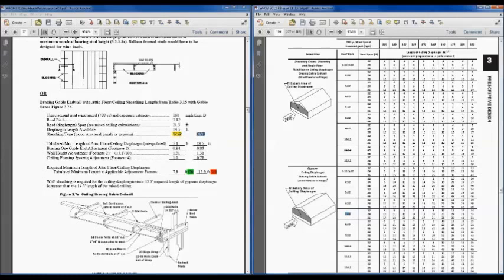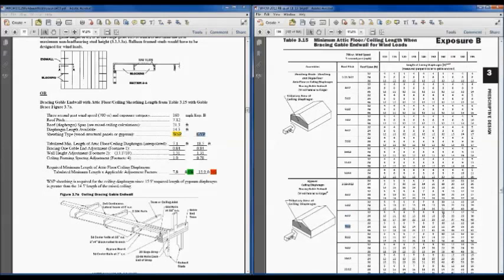Something doesn't seem right here for that interpolation. Give me just a second to get my bearings. Sorry about that. I may have misread that table at some point, or maybe I'll figure it out here in a second, but I'm thinking it's supposed to interpolate between 21 and 35 feet. We, for some reason, have 18 feet here, and with the adjustment factors, it ends up showing 16 feet of gypsum. So we know that gypsum in this particular case won't work.